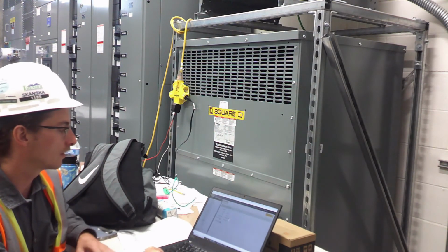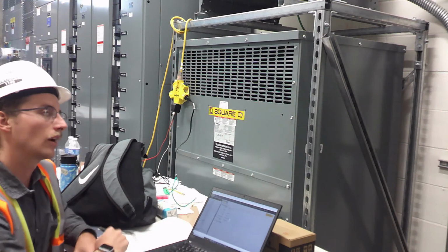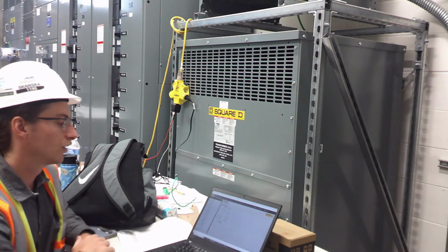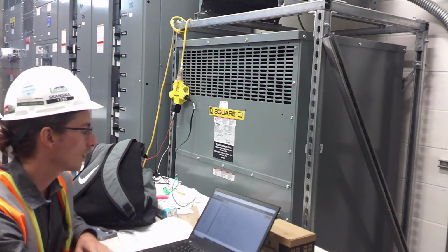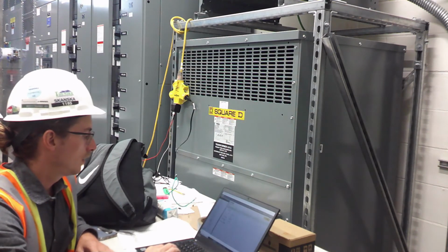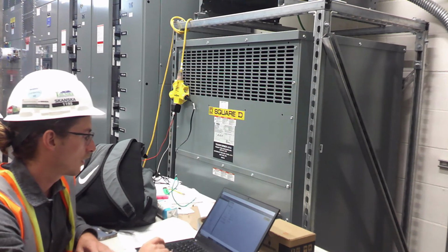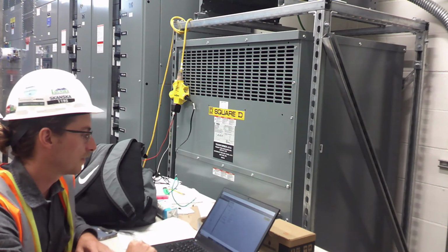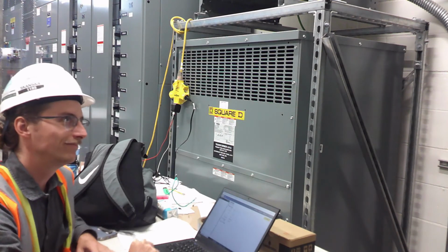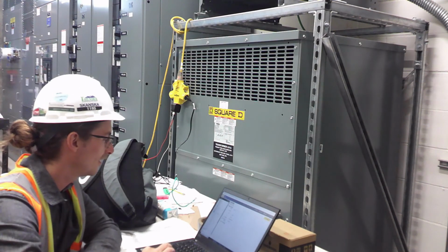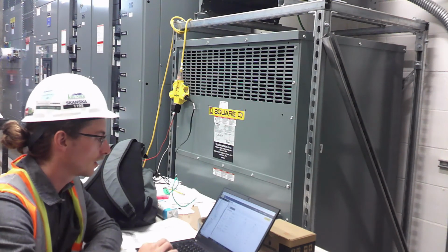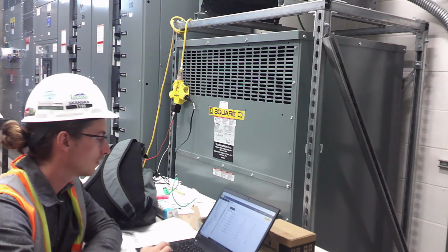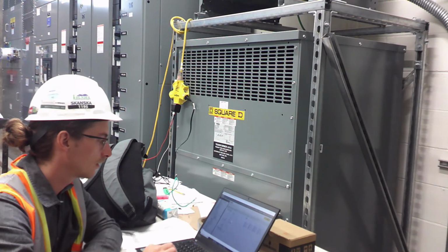So just go ahead and hit save, and that's going to put the area and zone settings down to those relays and occupancy sensors for that stairwell. And I'm just going to take a second to set the programming on that so I don't forget. Let's see, so I'm going to go stair 11. I'm going to set the close to open. Oh, looks like I already got that in there.